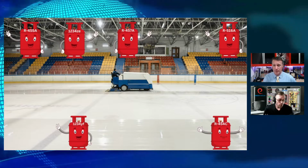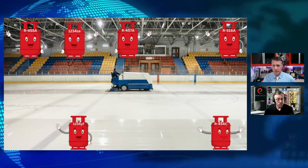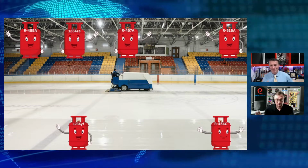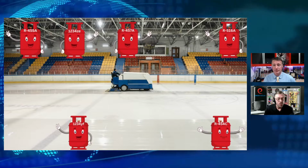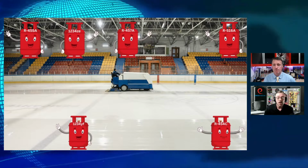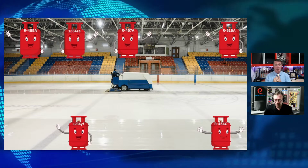There's another one that I want to point out that's probably currently out there that is low GWP, and it's ammonia. Oh, absolutely. A lot of people don't realize, when we think ammonia, we think, oh, it's toxic. But it is also a 2L refrigerant. It is also mildly flammable. Right. The big thing there is the hazard that becomes acute first is the toxicity, but it is a 2L refrigerant. Exactly. Good point, Jason. Glad you brought that up.